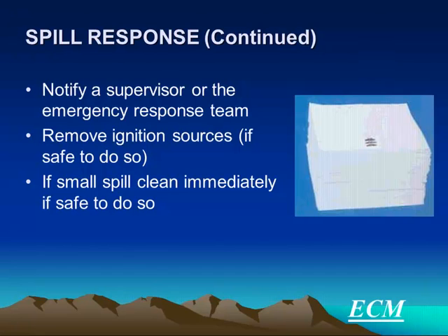that's spilled. There's actually a rule that OSHA has, and the fire department's going to do the same thing. Any circuit boxes have to be clear for 36 inches in front of them. You may have seen black and yellow tape on the floor so nobody puts brooms or whatever against the circuit breaker box. That's the thought there.